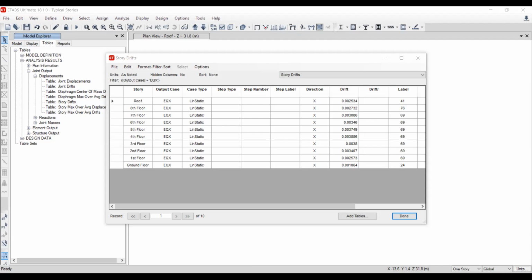I will consider this as we have a building frame system. Okay, steel, concrete with shear wall. We take this one, concrete with shear wall, and take 5.5. Or you can take this one also, moment resisting frame system, for the ordinary or intermediate 5.5. So based on what type of system you have, you can select the response modification factor. So again, go to page 16 and use this equation for checking the story drift.